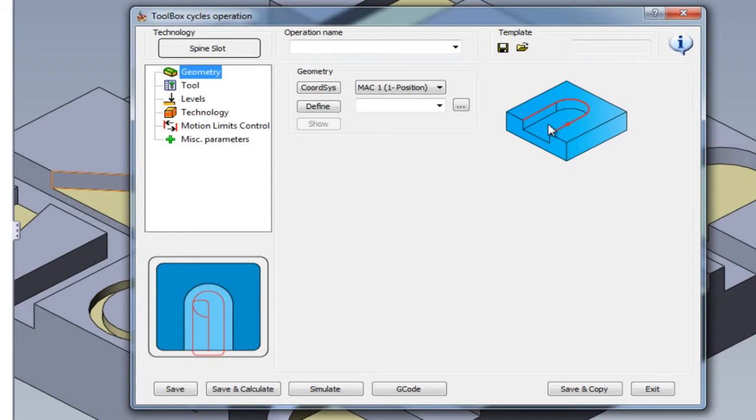In this particular case, the tool will go down the middle and then off to the side, clean one side, go out, and then clean the other side and turn out from that area over there. The geometry in this particular case is the top lines over here, the top chain over here, and this is left open. We do not choose that area at all.